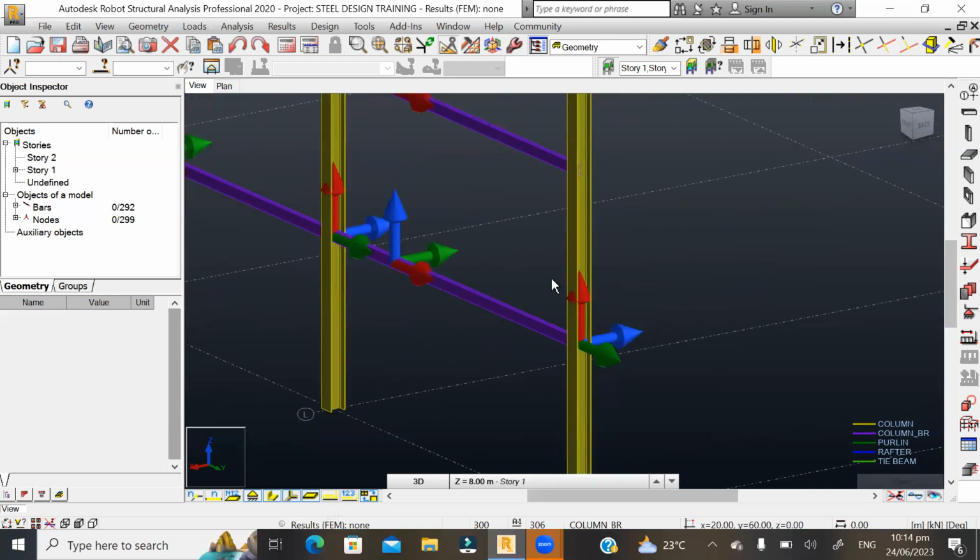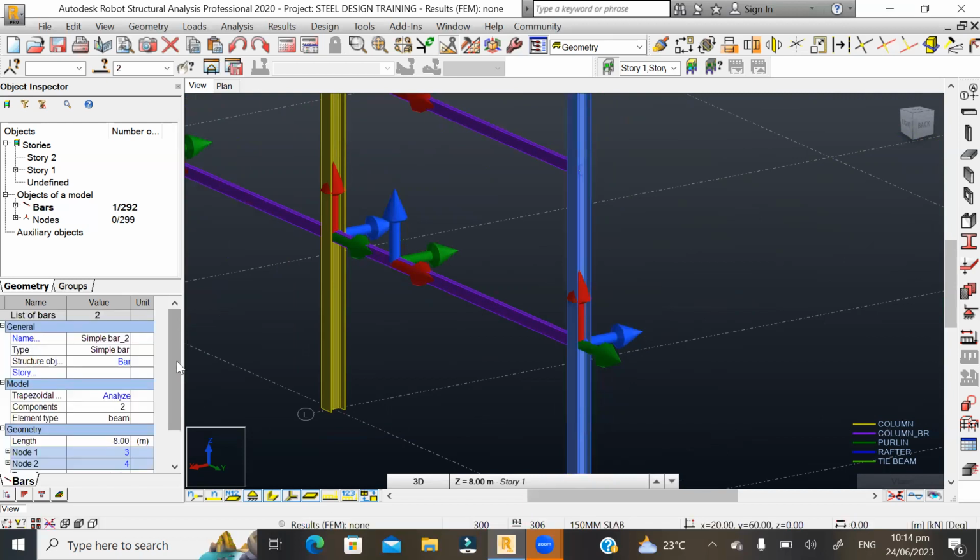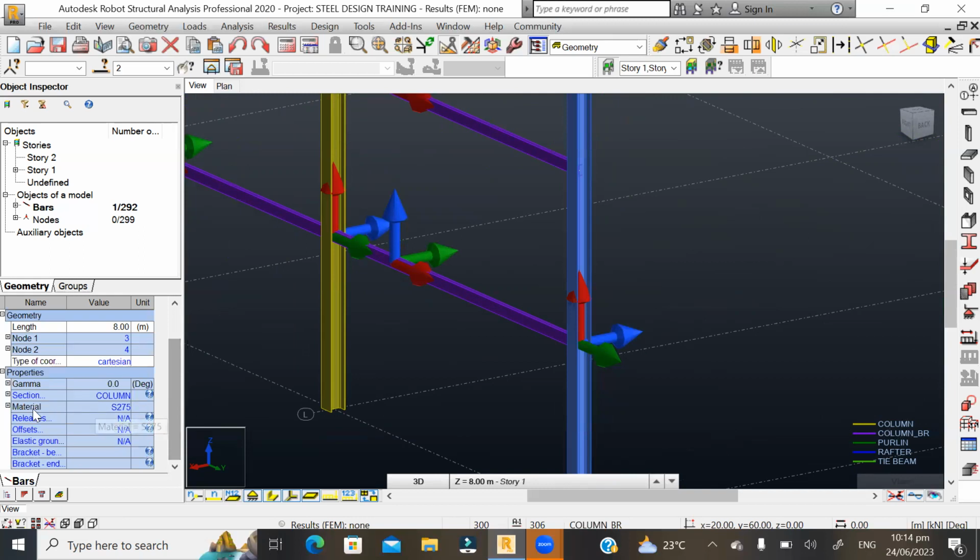So to make it point outside, I'm going to click on the member. Then I will come here under the gamma angle. You see something like a gamma here. So you click on this plus to expand it. Then you begin to increase the angle till you have the Z coordinates outside the model. So I will start from angle 90. I'll press enter.